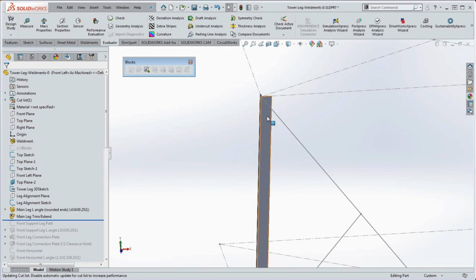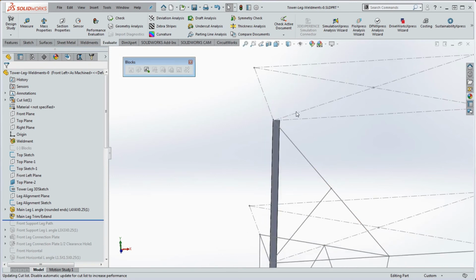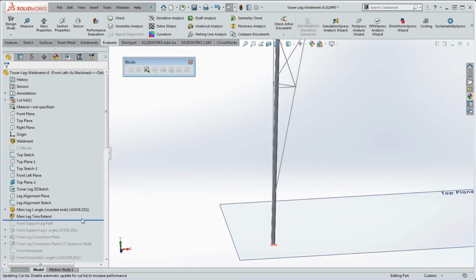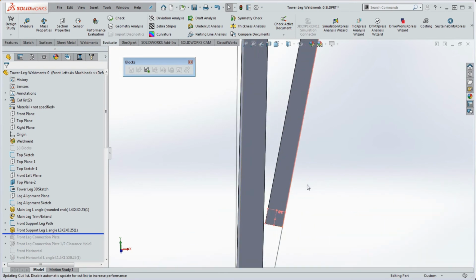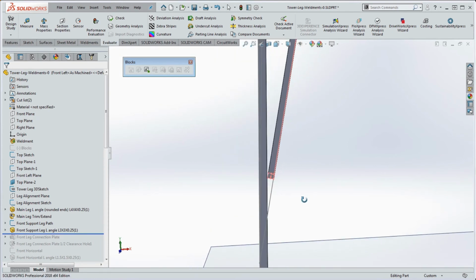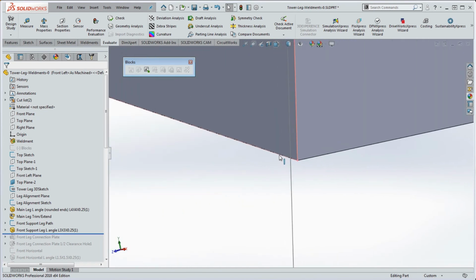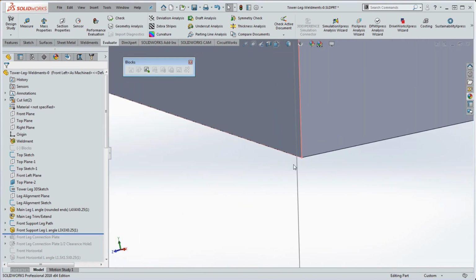It's got a direct relationship with the 3D path, or 3D sketch in the background, a 3D design sketch. Everything else is going to be stacked. So when I put in our support leg over here, which is going to be the next element in here, this is actually going to be coplanar with that surface. And when you make it coplanar with that surface in here, it's just a little bit set off from that 3D sketch, design sketch line. If you take a look at this and kind of scoot in on that because of the angles involved, this is our 3D sketch line, which is kind of in front of that, and this is our pass segment line, which is a little bit behind that.